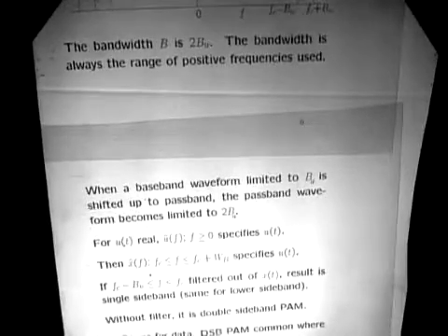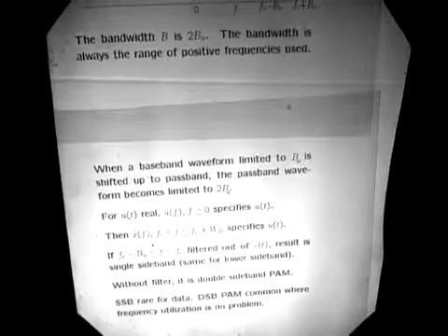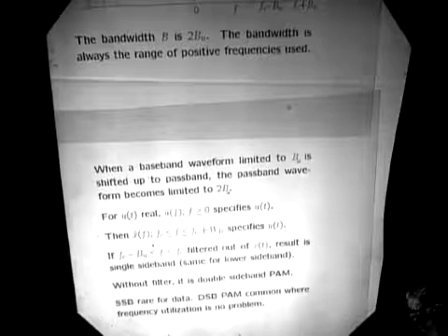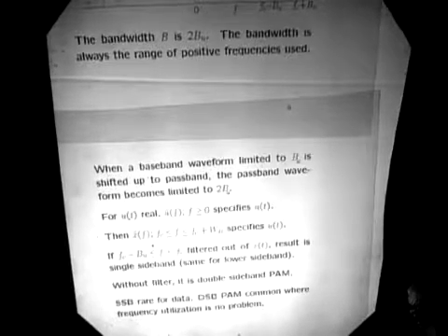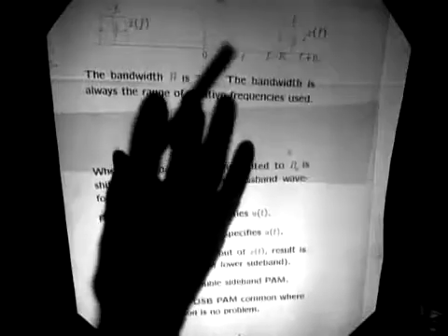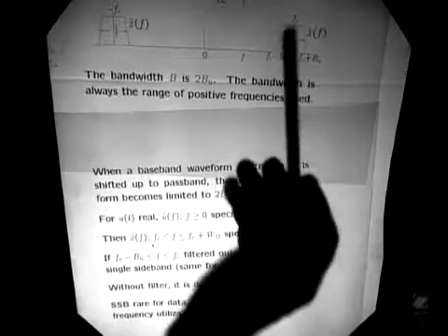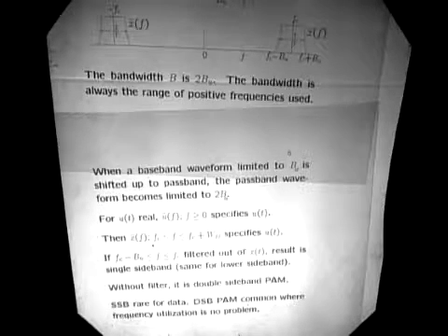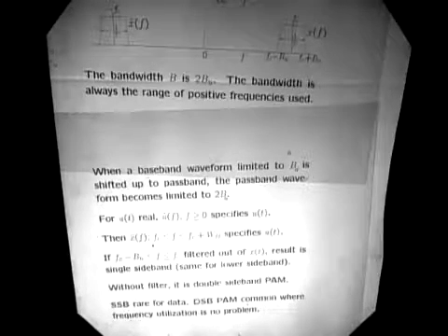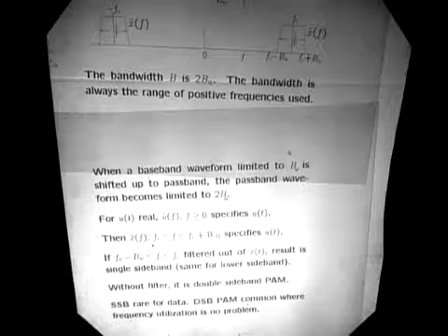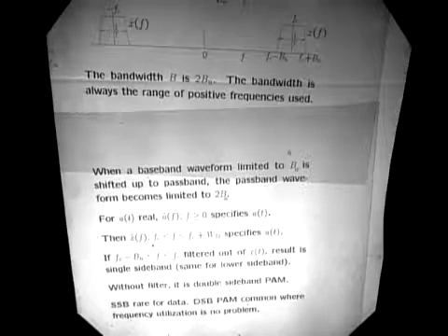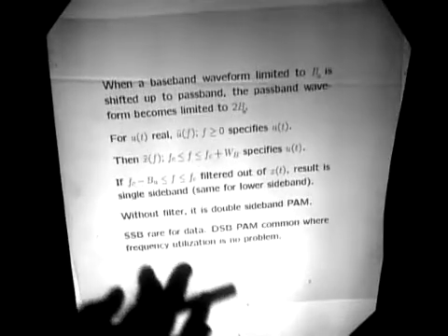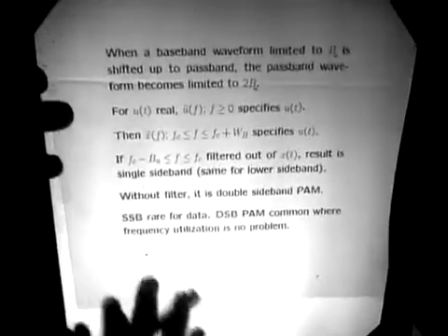It's not the usual way of doing things, partly because these filters become very tricky when you're trying to send data at a high speed. All sorts of noise in here when you try to do this and you don't do it quite right affect you enormously. And people have just seen over the years that those systems don't work as well as the systems which do something else that we'll talk about later, namely QAM, which is what we want to talk about.